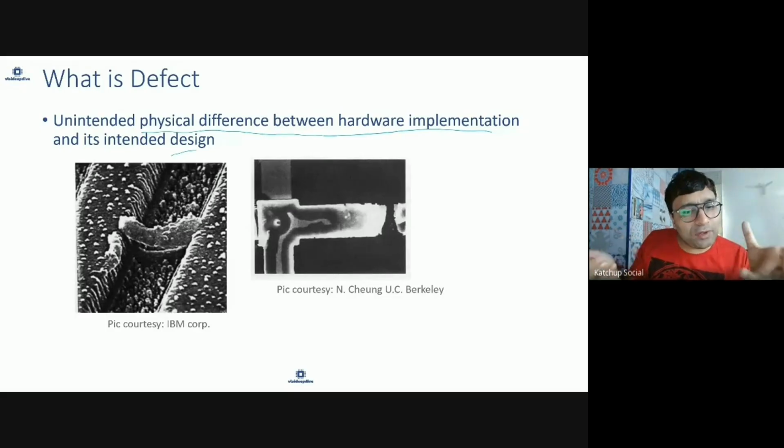For example, when you're manufacturing, fabrication is not 100%, so some nets can be unintendedly connected, and some opens may stay there unintentionally, and that can cause the chip to fail or not work correctly. You don't want to ship these chips to your customer. Apple does not want to give a phone which has this kind of defect.